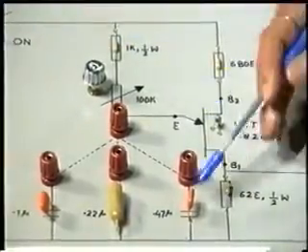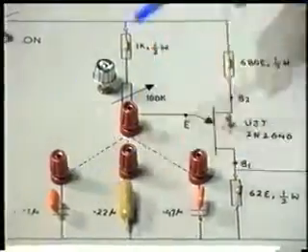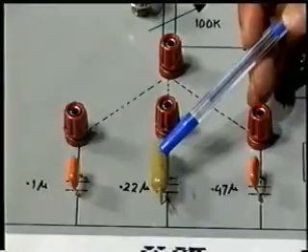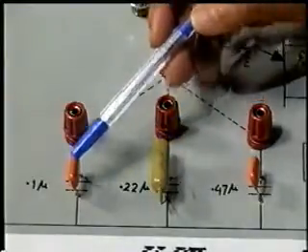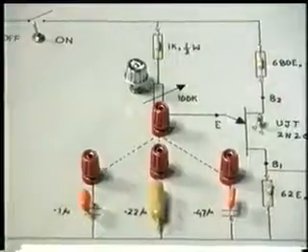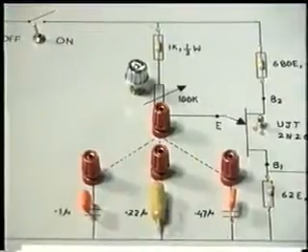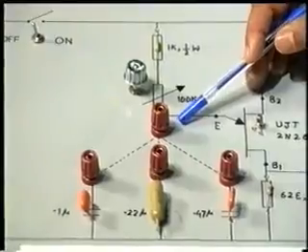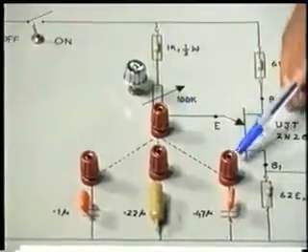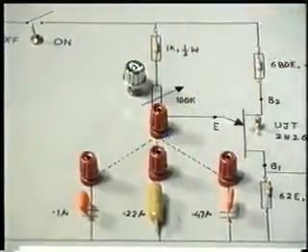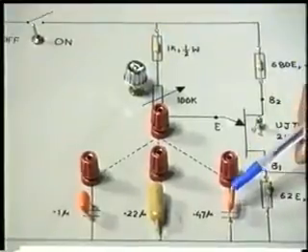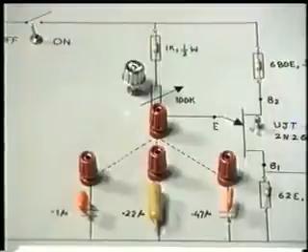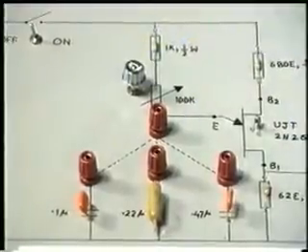Now you have 3 capacitors here. This is 0.47 microfarad value, this is of 0.22 microfarad value, and this is of 0.1 microfarad value. This has been purposely done to make the experimentation more interesting. This is the common point, so I can connect one terminal here and one here or here or here. By that we can connect either this capacitor in circuit or this capacitor or this capacitor. So we can have different wave shapes, right.